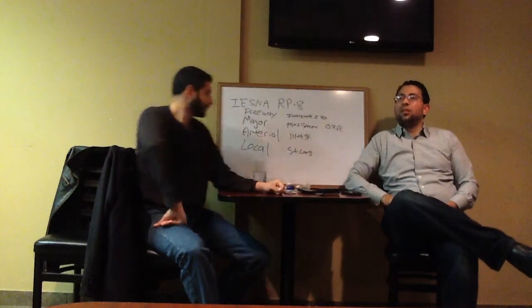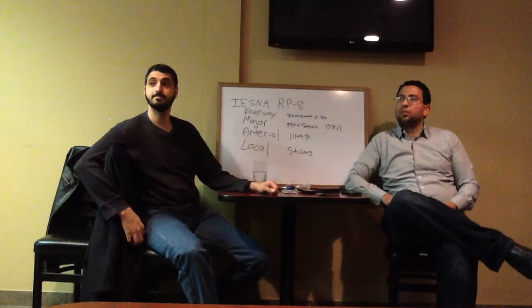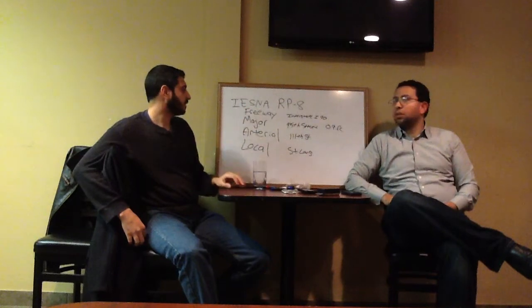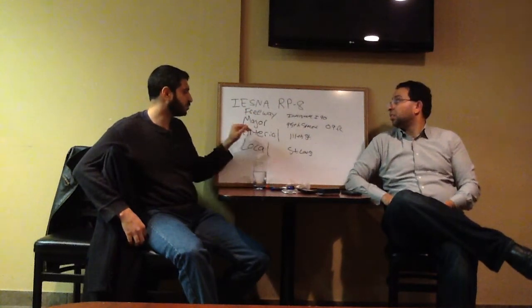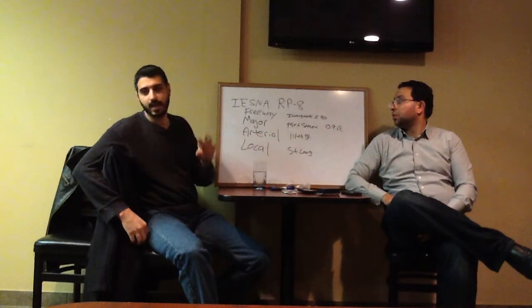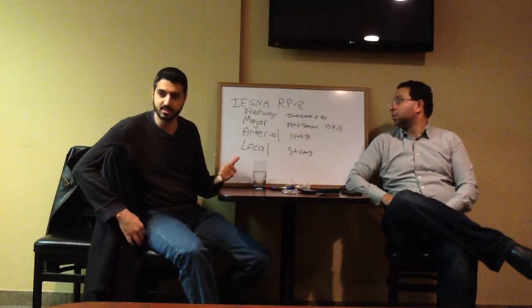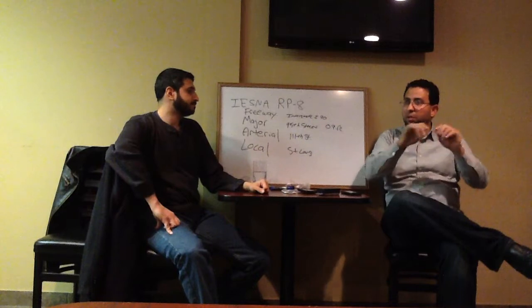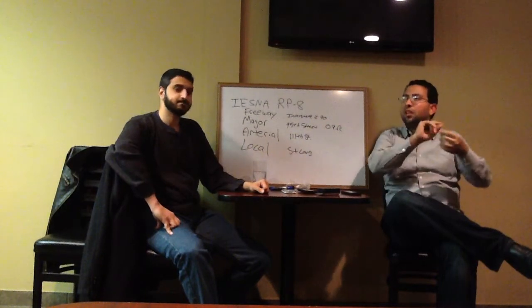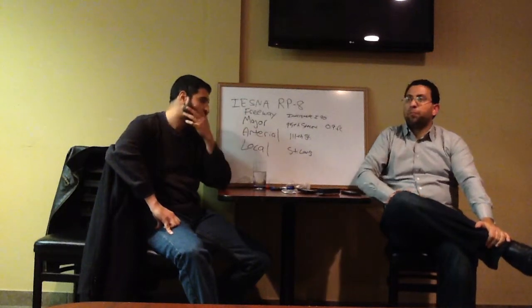For these categories you gave, what are the foot candles that are required, let's say as a minimum? For the freeway, it's 0.9 foot candles. For the major arterial and local, I have to have the RPA in front of me to give you exact numbers. I don't have it memorized. But those are the very basics. When you go to the table, it states exactly what foot candle level you have to get.